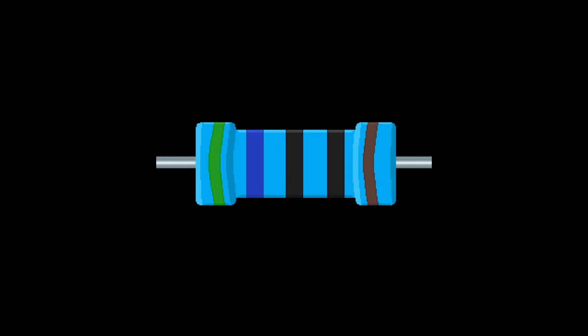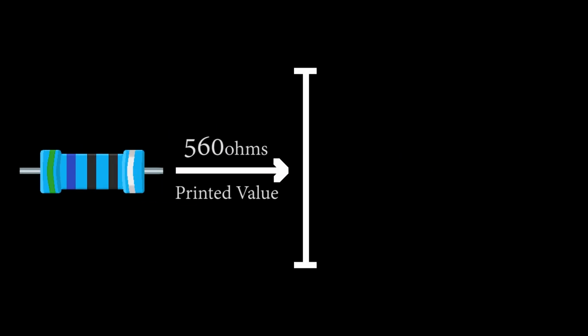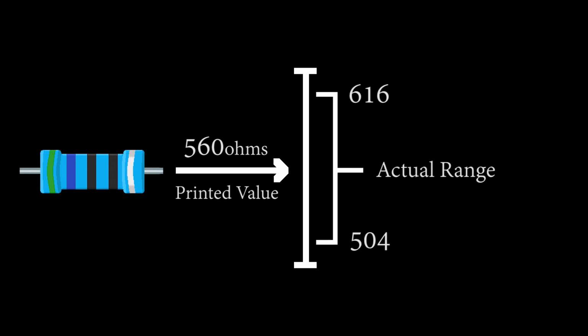A resistor with a silver band as the fifth band, or 10% tolerance, means that for a 560 ohm resistor, you can actually see values between 504 to 616 ohms. Tolerance shouldn't be an issue with our Zoombot project, but just know that high tolerances can ruin circuits that do require precision.